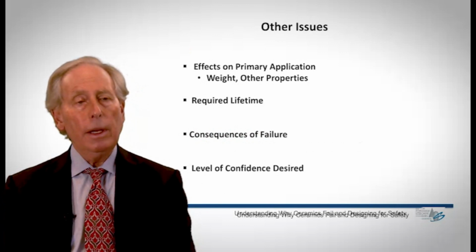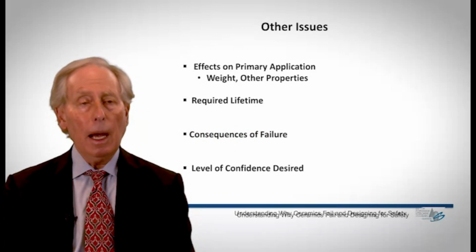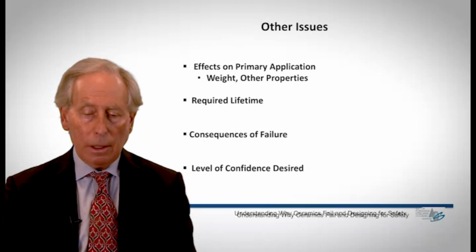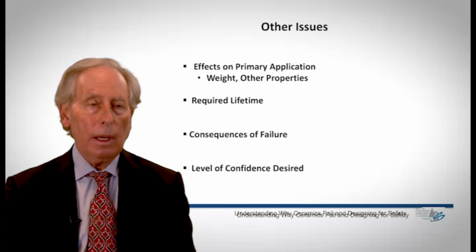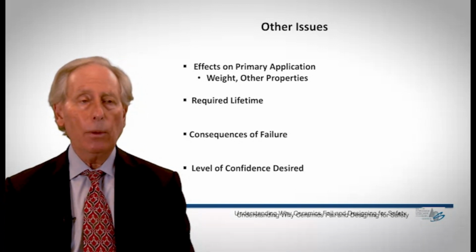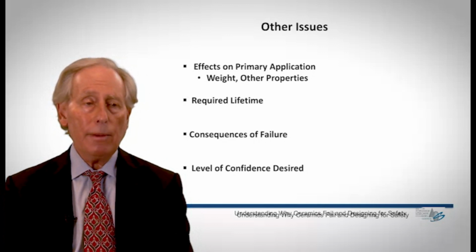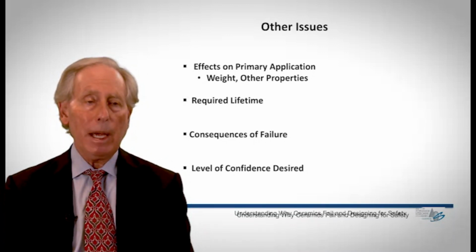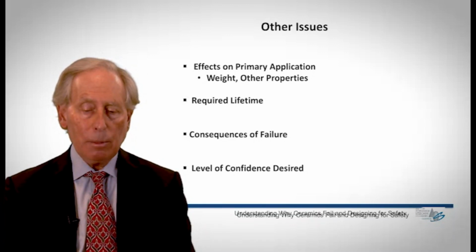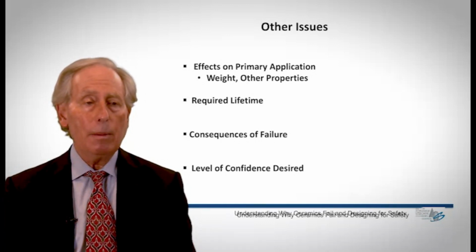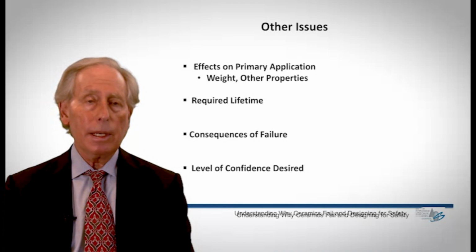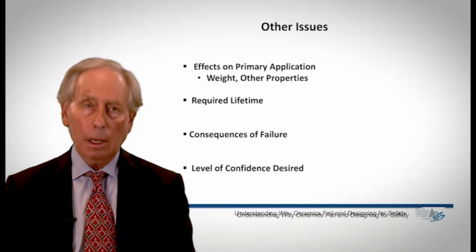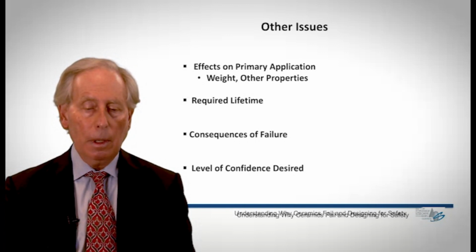First of all, the effect on the primary application. Obviously, the weight of the material is going to be important. I can't over-design. I can't afford to do that. I can't make the part too heavy. I can avoid failure simply by making the part large enough, but that probably isn't going to be very useful. What is the required lifetime? Is this a part that's just going to see a few minutes of operation, or is it going to be in place for years? Something to think about.